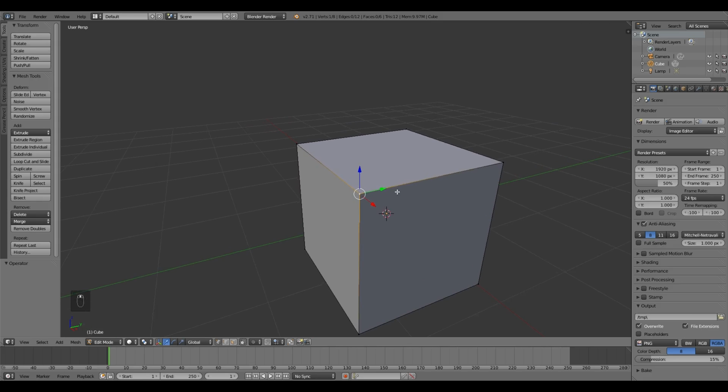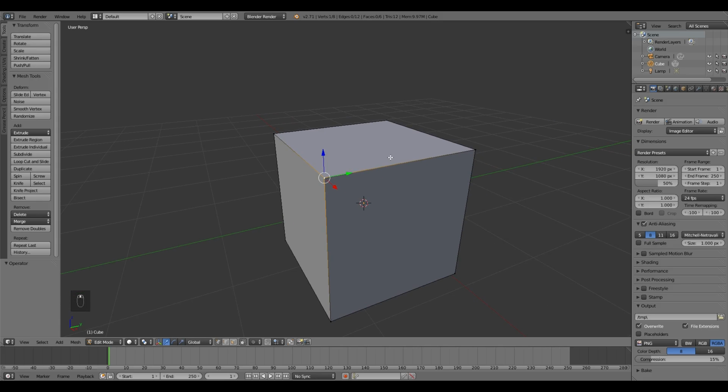Alright, next in line, it isn't just vertices, it isn't just the corners we can manipulate, we can also manipulate the lines. So you have these little dots, and you have these lines connecting the dots. This is known as an edge. Now if you follow my mouse down, hopefully shown in the recording, go down to your panel, see where it has the word global, and beside it you have a little square to the right, it's a little dot. And if you let your mouse hover over it, the words vertex select will pop up. Well, if you click the button beside it, hover, it will say the words edge select. It has a yellow highlighted line.